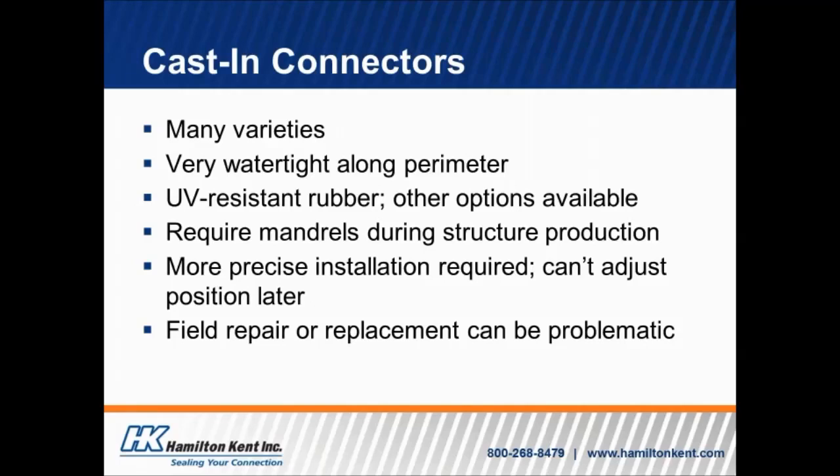It requires much more precise installation. So when it comes time to cast it, a precaster has to be very careful about making sure they have the exact position, because once the connector is cast in, there's just no changing it. Now they could core a hole there, and if they need to adjust the size, put a boot connector in there, but it does require much more precise installation.